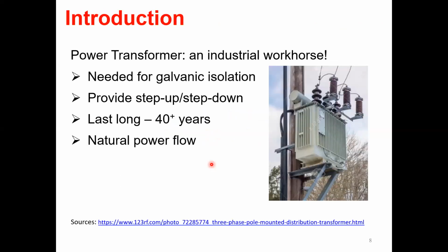So let me begin with a brief background of transformers and power density. Like I mentioned, our talk will be primarily on the higher power transformers. Primarily we need them for galvanic isolation, and for step up and step down. The step up and step down is what actually defined the main purpose of transformers, because that made long distance transmission possible. You didn't want a lot of loss in the transmission lines, so once we were able to step the voltage up to a high voltage, that enabled long distance transmission.